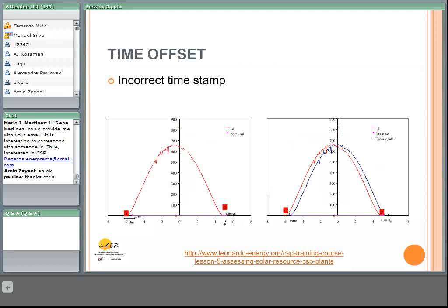Another very common problem is the problem with the measurement of time. In a good solar radiation measurement station, time should be measured precisely. That means it's important to have a very precise time on the data logger, because solar radiation depends on time, and if you wish to later apply some models or make some quality control tests, you will get incorrect results if the time is wrong.